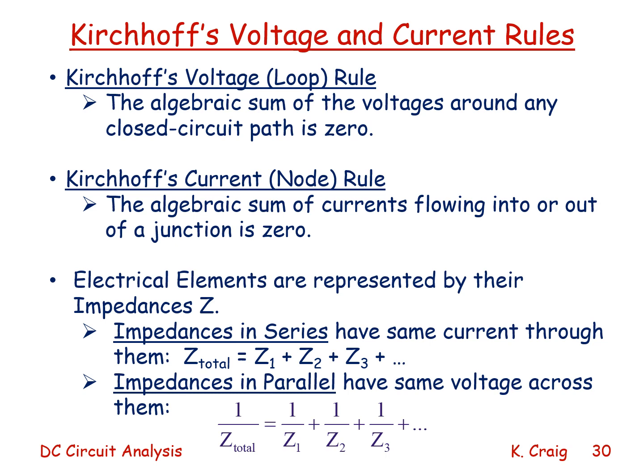Impedances in parallel have the same voltage across them. The reciprocal of the equivalent impedance is equal to the sum of the reciprocals of the impedances in parallel.